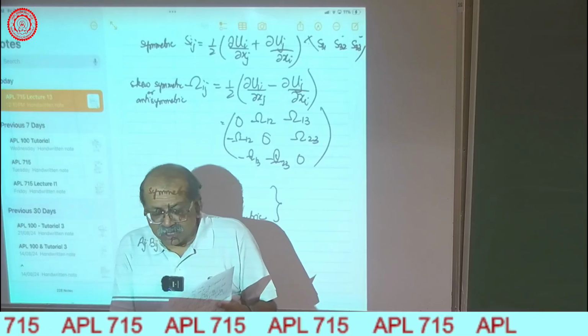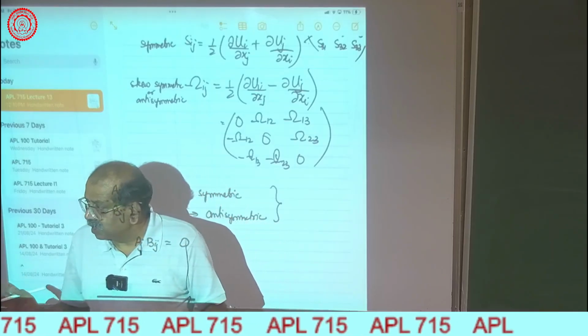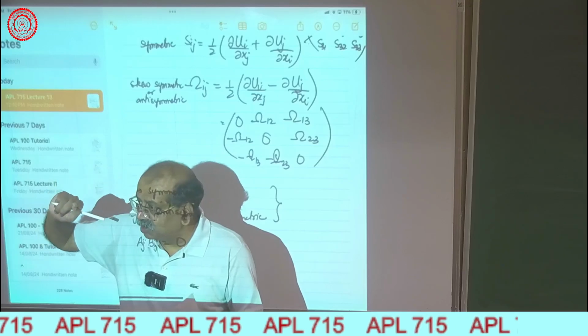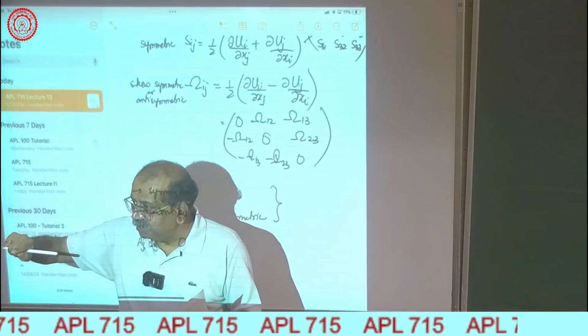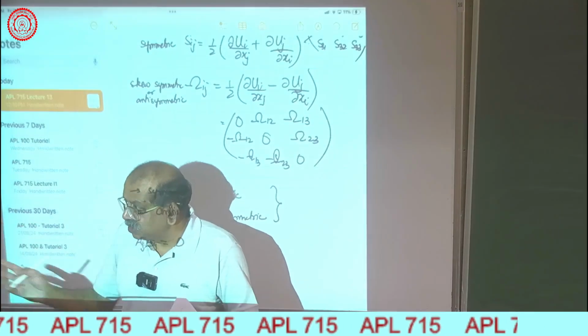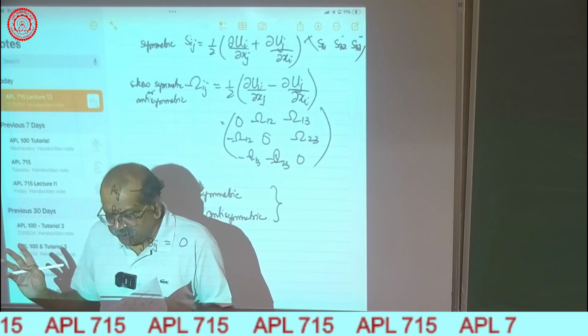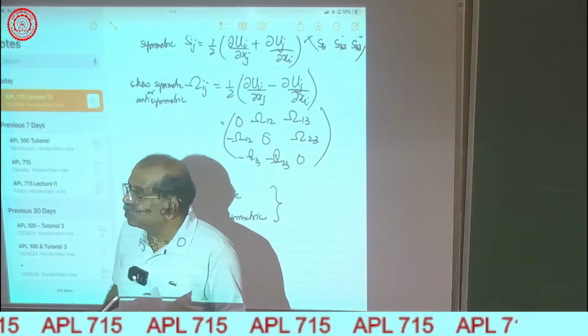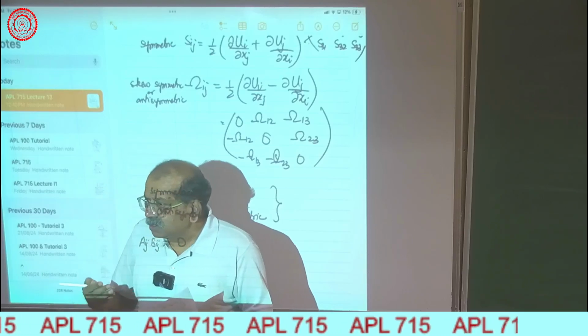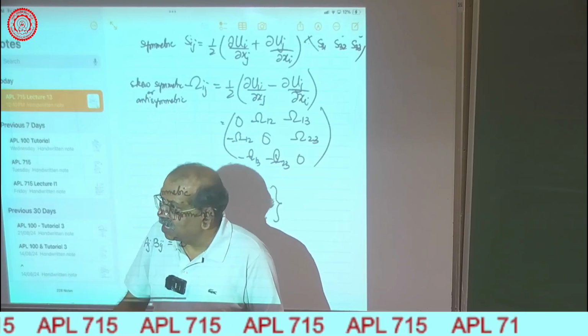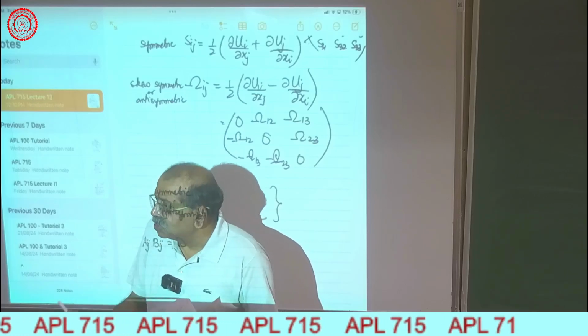First you write the equation for u_i prime u_j prime. I had already told you: you take the equation for u_i prime, remove all the j's. If anything is summed upon j, call it k or l, best is to call it k. And then multiply that equation by u_j prime. The same equation you copy down again, but interchange i and j.